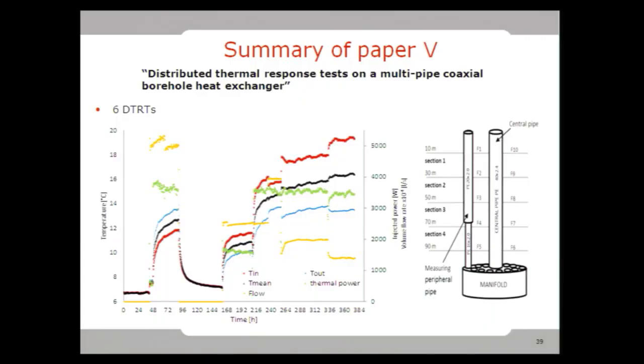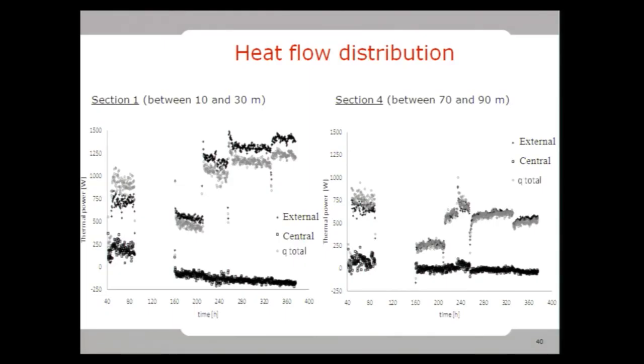And the borehole for the local analysis was divided as shown in the picture on the right-hand side. So it's 4 sections, 20 meters long each as well. And you can see a particularity here: the pipe through which the optical fiber cable was inserted had to be changed in dimension due to practical issues. So sections 1 to 3 have a slightly larger measurement pipe, which ended up not giving any differences, as you will see.